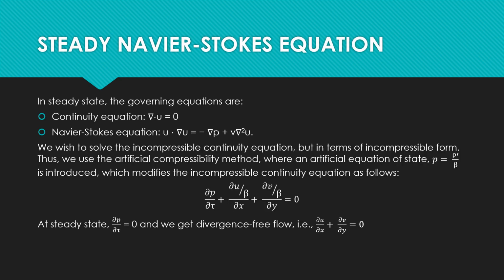We have previously worked with steady-state governing equations, which are given as follows. This is the continuity equation, and this is the Navier-Stokes equation. With steady-state equations, an artificial equation of state is introduced while solving the problem with artificial compressibility method, as it is given over here.